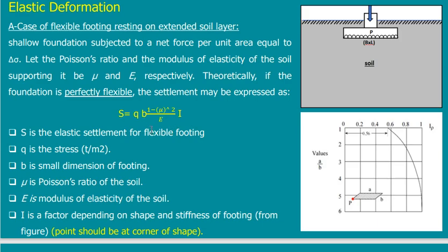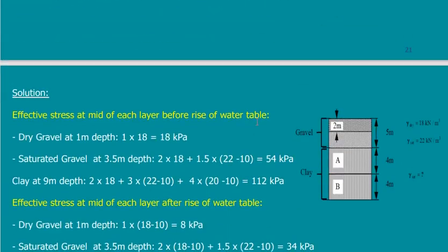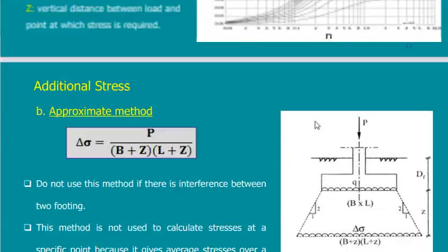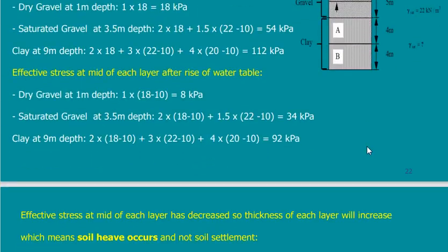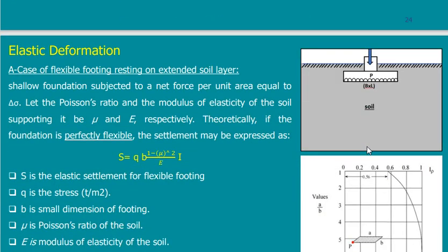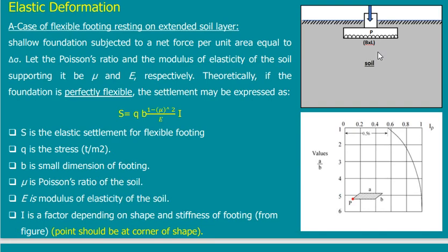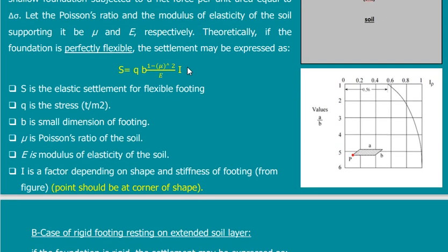In this case I don't use the equation that I will be giving now, because I will go back to what we have used before and consider that the area that will settle is, I know exactly what is the depth of the layer, because I assumed it approximately. But if I want to calculate it using these equations, then I can use this equation instead and not assume any fixed boundaries. So for this case, I have two sub-cases.